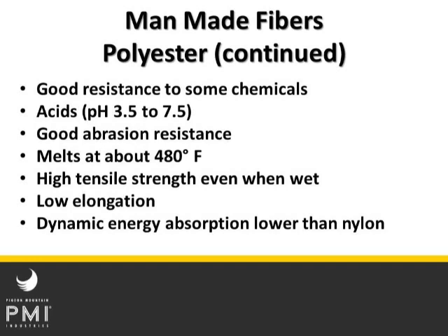It has good resistance to some chemicals. It likes acids better. Its pH range that it likes is 3.5 to 7.5. So if you guys are going to rappel into tanks full of 3.5 pH acid, pick your polyester rope to do that, and good luck. It has good abrasion resistance, melting point 480. It does maintain its same strength when wet, unlike nylon, which reduces a little bit. And it has a very low ability to absorb dynamic energy compared to nylon. It's not a great choice if you plan on taking a fall.